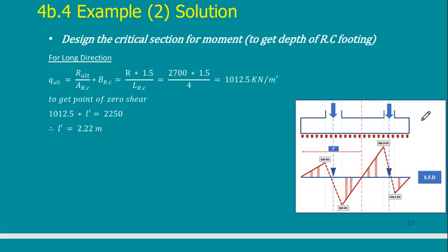Now I have a beam, similar to a plate, that has two loads on top and soil reaction from the bottom. You can draw the normal force, the shearing force, and the bending moment for this beam. This is what we need in our design. So I will just get the value of these loads.